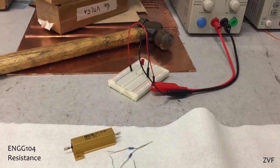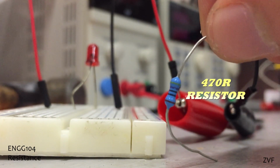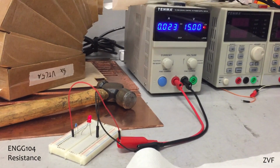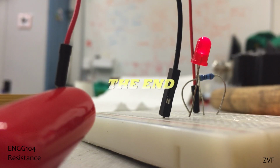Recall then the LED. The current through the circuit may now be controlled. This is a 470 ohm resistor, which should draw a current of about 27 milliamps. Success. Yet this is but a simple application of resistance, although it is foundational in the design and analysis of circuits.